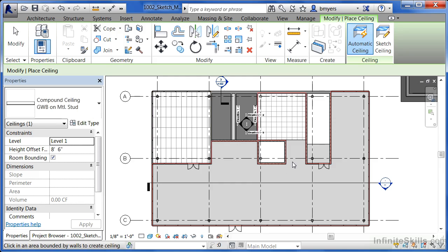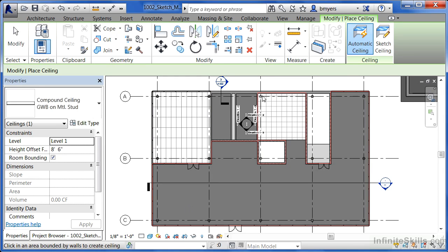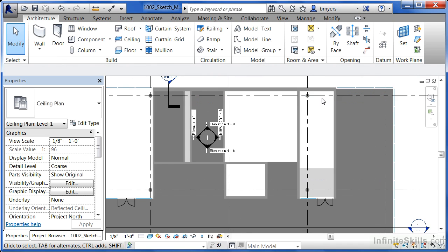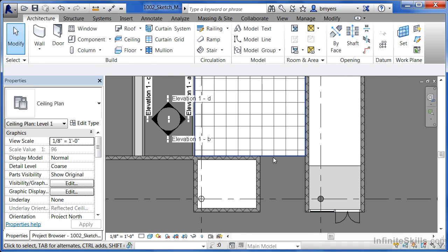Click right inside of the space. We can see this is all turned gray. But even though this pattern hasn't changed, I can tell you that there's actually 2 ceilings inside of this space. I'm going to hit escape right now. Now I'm going to put my mouse over the edge of where I know a corner of the ceiling is at. And I'm going to select on the tab key to try to select my different ceilings.